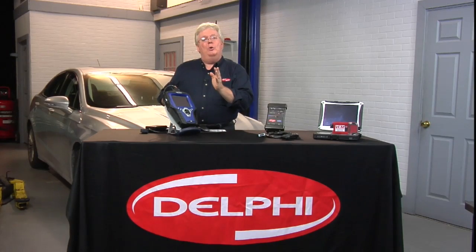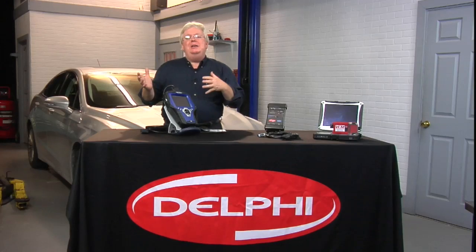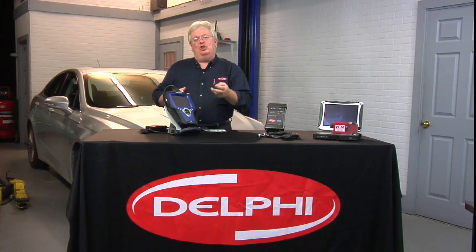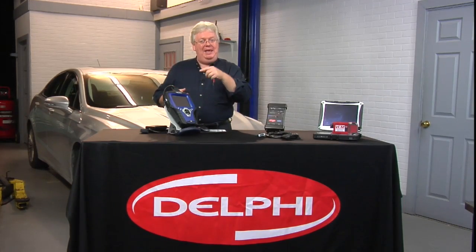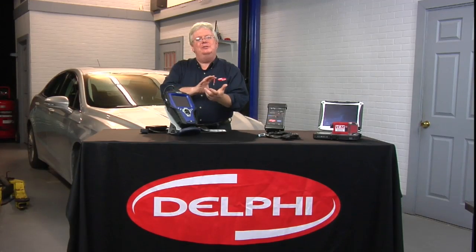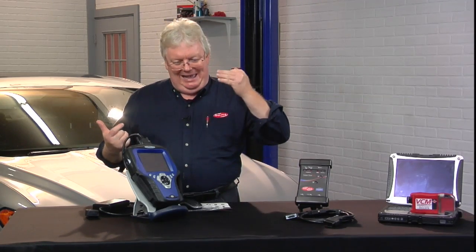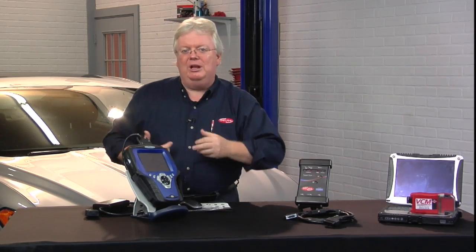So you need to know if the car you're working on has CAN before you do much diagnosing and research in what we're going to see coming up next, the websites of resources from your factory OEM internet information provider. So we're going to look at that, but we need to know if it's CAN or non-CAN.